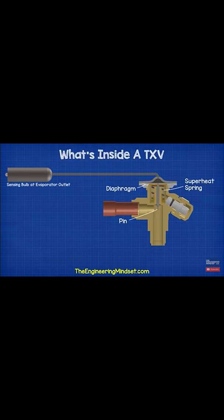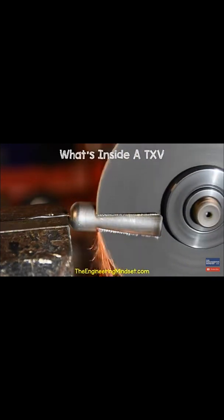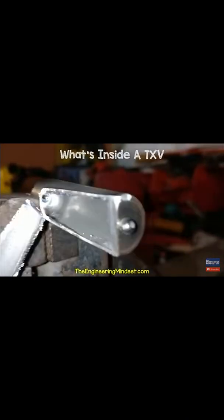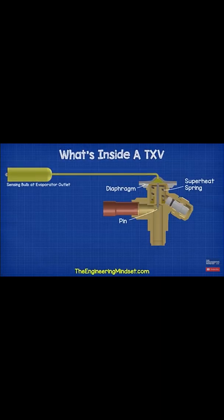We can use this to adjust the superheat, and we'll look at that a bit later in this video. Above the diaphragm, we have this empty chamber which is connected to the capillary tube and then the sensing bulb. The chamber, the capillary tube and the bulb are all hollow. I'll just cut through the sensing bulb using an angle grinder to show you the inside. As you can see, it's just an empty cylinder which is usually filled with some refrigerant. The refrigerant in the bulb and capillary are completely separated from the main refrigerant which flows in the system. This isolated refrigerant only moves between the bulb, the capillary tube and the top of the diaphragm.